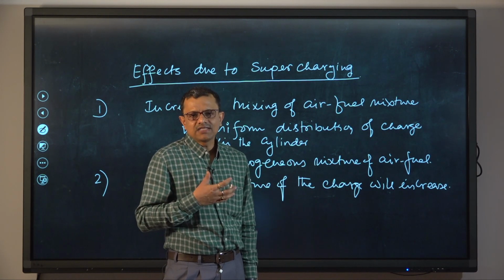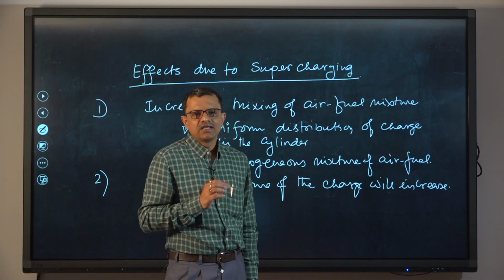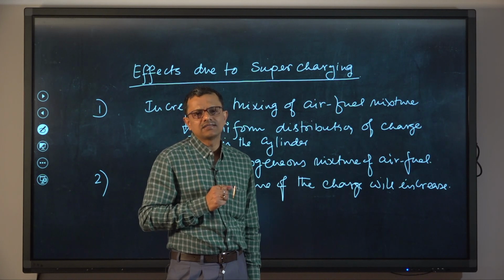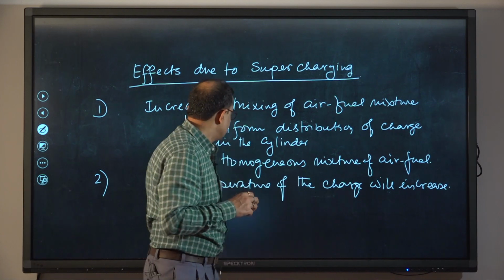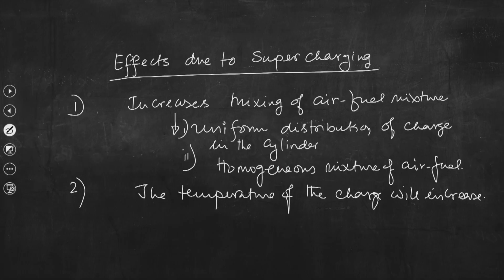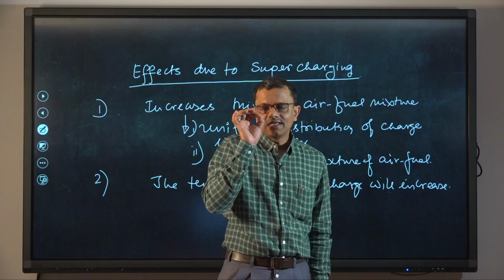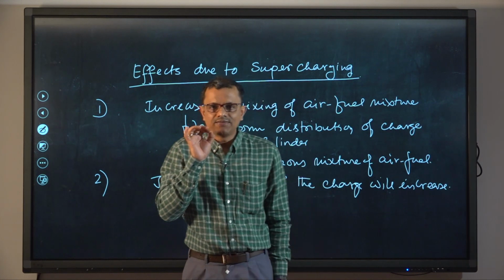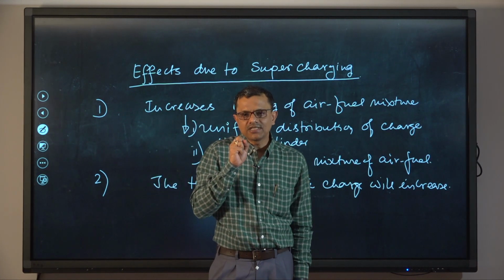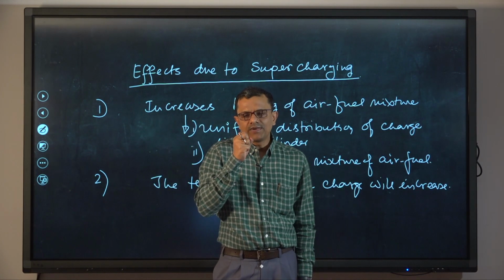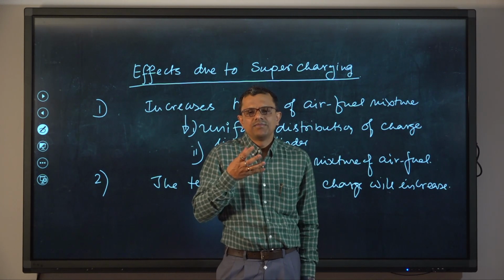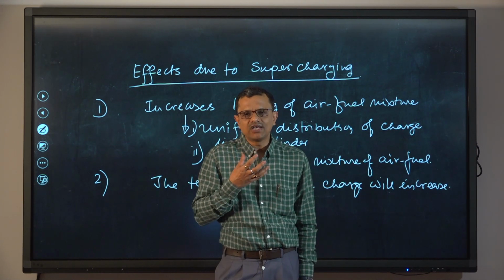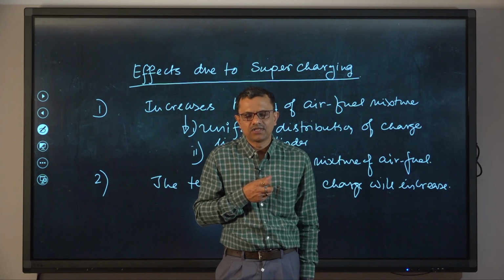This temperature rise will have some favorable and some detrimental effects. The favorable effect is that, since fuel is injected in the intake manifold, the higher temperature will allow fuel droplets to vaporize completely. So, it will help better vaporization of the fuel droplets sprayed into the intake manifold.